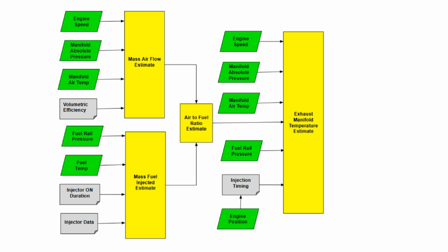Even though these time delays may all add up to less than a millisecond or two, if you get the injection timing wrong, the engine performance and the exhaust emissions are really going to suffer. The good thing, though, as technicians, is that a problem with the crank position sensor may cause a problem with engine speed measurement as well as crankshaft position. Hopefully these types of failures are rare, since they're probably going to cause the engine to not run at all or to run very poorly. Ideally, we'll get a DTC that'll indicate that we have a problem with the crankshaft or the camshaft position sensor.